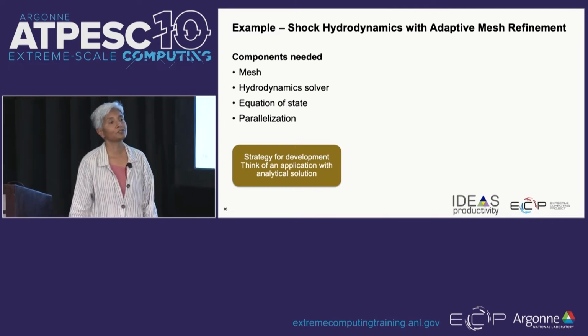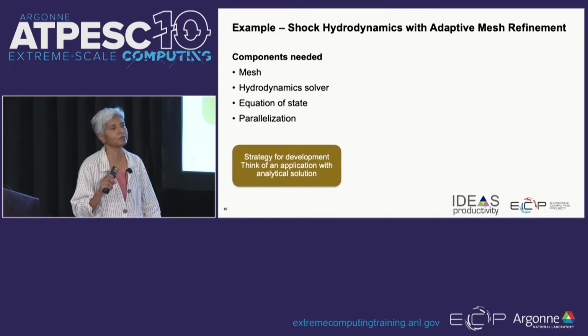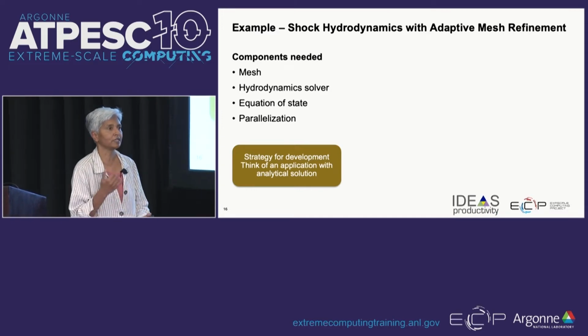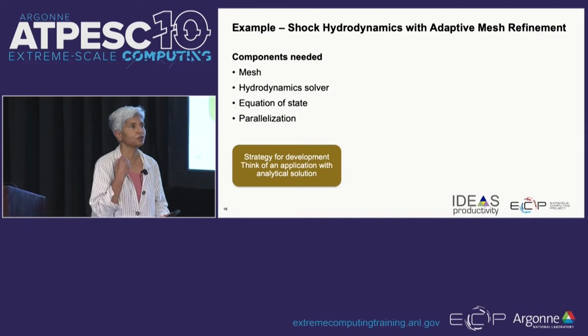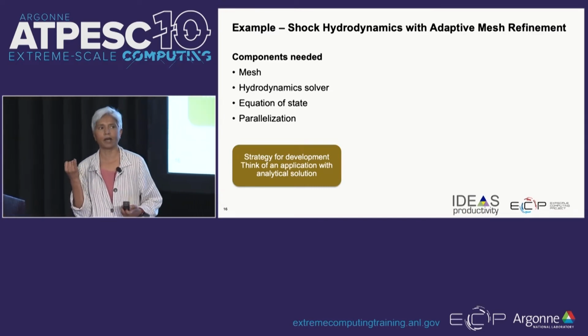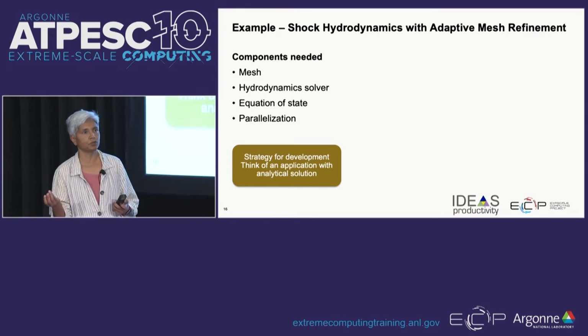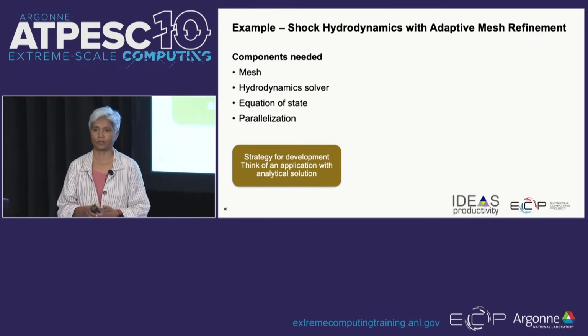Okay. So, you also know that in adaptive mesh refinement there is much more bookkeeping that goes on than just a uniform grid, in the sense that even if you are running stencil code in adaptive mesh refinement, you need to have reconciliation of quantities at fine-coarse boundaries, you do regridding, and so on.